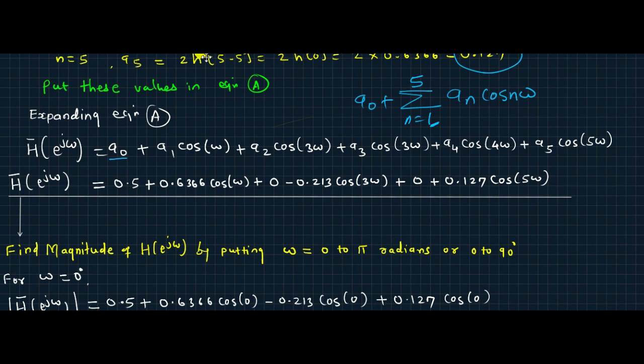What's happening here? The frequency is increasing. And what will be the response of the filter to increasing frequency? That is our test. We have to test the FIR system, in the ideal low pass case, whether it is allowing low frequencies and blocking or stopping the high frequencies. That is the check. That is the design of the FIR filter by using the Fourier series expansion method.